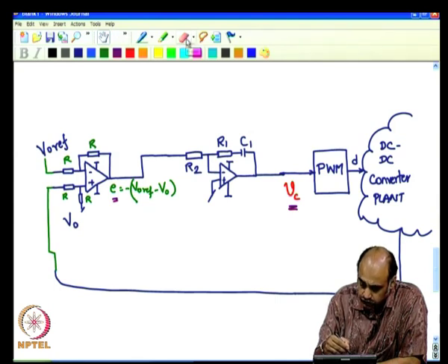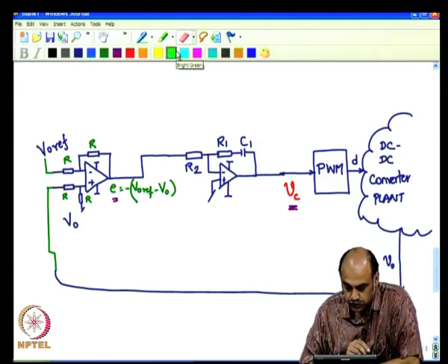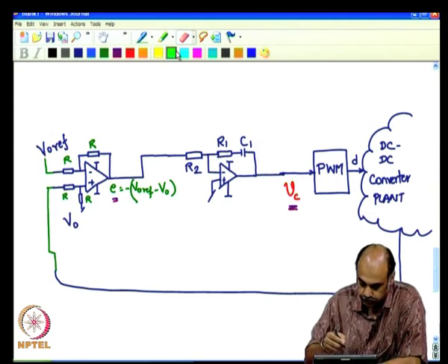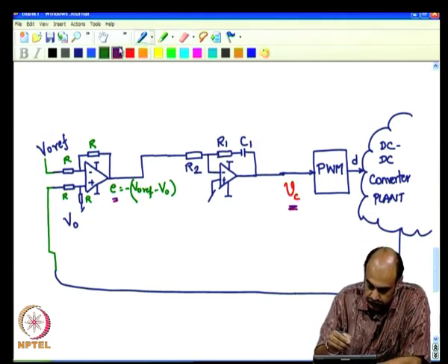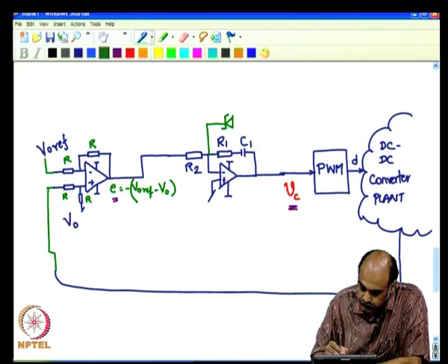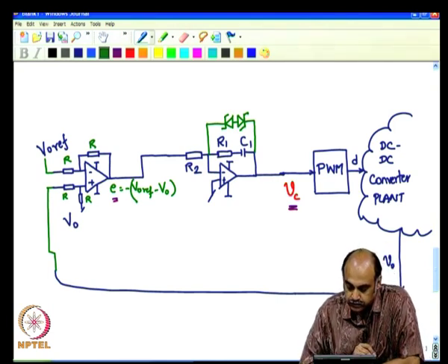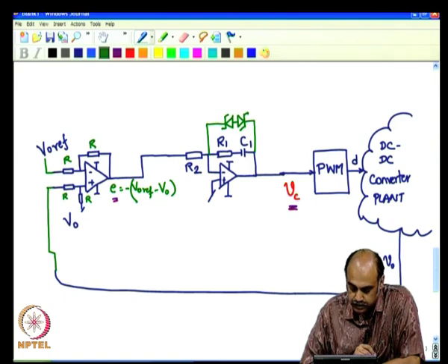Now, we could further reduce the controller if you want to. Of course, here do not forget that we shall always put 2 diodes, Zeners back to back to take care of the anti wind up. These are the anti wind up clamps.